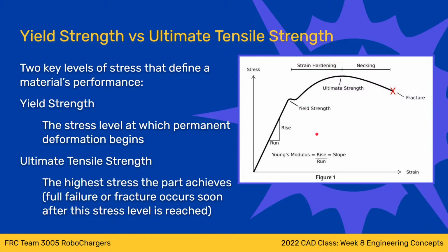This has different uses, but the thing to understand is what happens with a hard material. The material doesn't really bend, right? You apply a force, the material sees a strain, and then eventually the material just cracks. That's because there really is no plastic deformation region. The thing just exceeds its yield strength, goes right onto ultimate strength, and just fails right away. Whereas softer materials will bend a little bit easier.